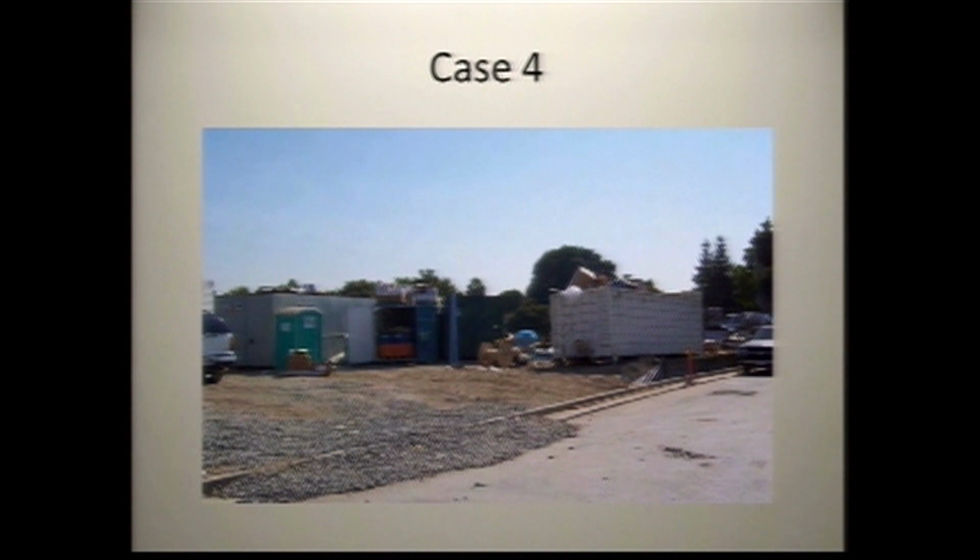You see the little amount of dirt or broken AC or something in the street? That's going to be enough for the regional board inspector to write it up. It needs to be just a little bit cleaner than that. You can see the silt fence kind of just dies and sort of looks messed up at that point. It's probably not a real clean ending to that. It needs to go all the way up to the track in, track out, which also needs to be fixed.